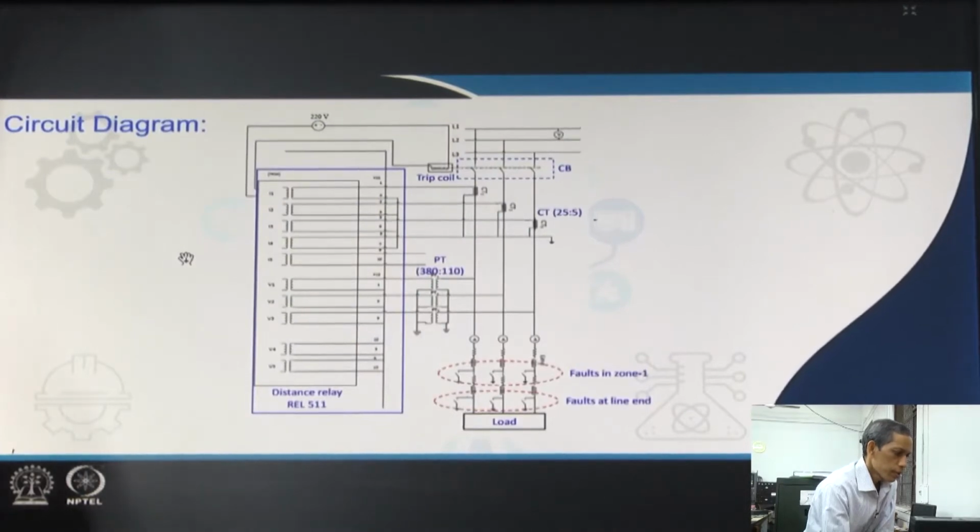So, we have a circuit connection for this. What we see here represents our transmission line model. We have in this setup 3 coils of inductance. These inductances have their own inductance and resistance associated. So, that is our transmission line model, and they are not mutually coupled.